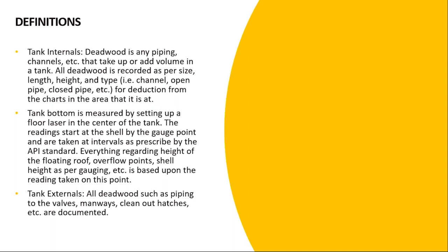physical properties of the tank, to estimate via calculation, via computation, the volume and the actual volume of the tank and correlate that to level, to product level within the tank. So that's what we want to do when we calibrate a tank. We want to get an accurate correlation between level within the tank to total or actual volume of product.